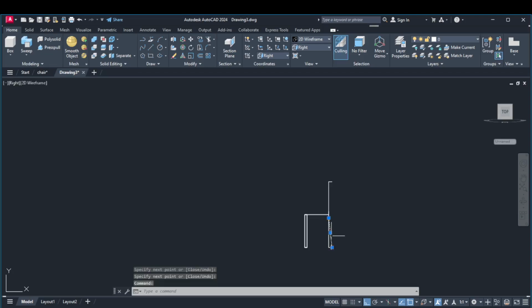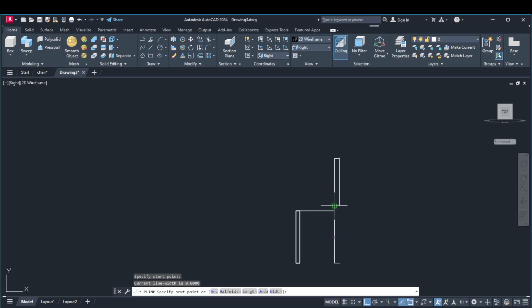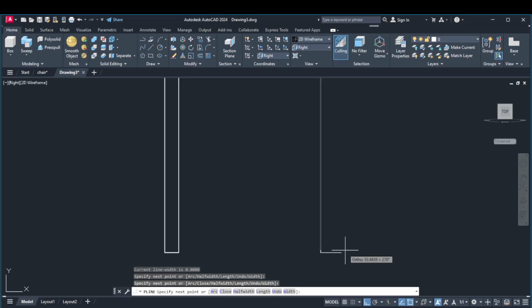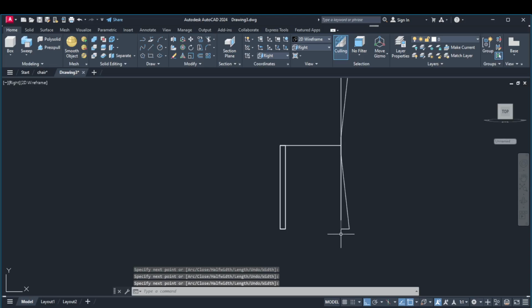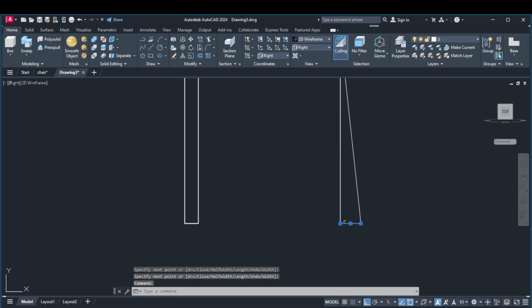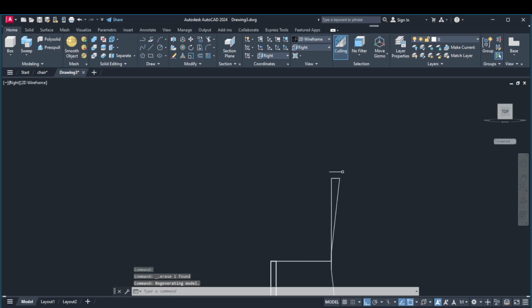Okay, so we can delete this line, then we pick polyline, then from polyline we close from that region to that end region, then to another end region here, and then to this end point, enter. So we can delete those unnecessary lines, those that are just construction lines. They assisted us in one or two steps, so we can delete them.